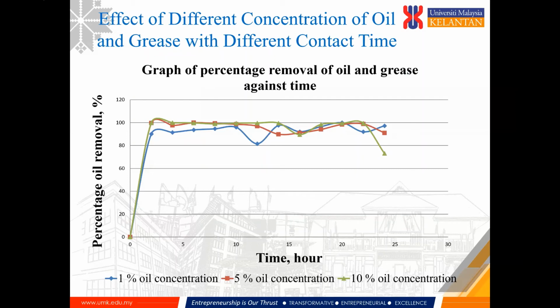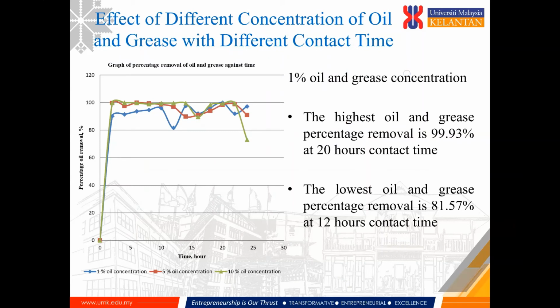For results and discussion: effect of different concentrations of oil and grease with different contact times. The figure shows the graph of percentage removal of oil and grease against time from 0 to 24 hours. For 1% oil and grease, which is the blue color, the highest percentage removal is 99.93% at 20 hours contact time, and the lowest percentage removal is 81.57% at 12 hours contact time.